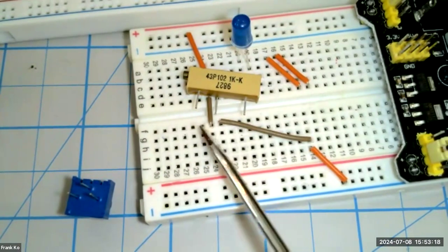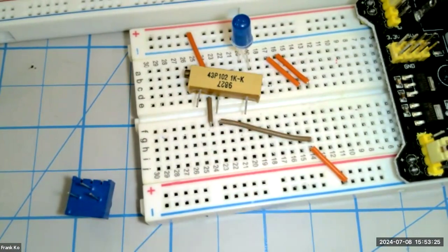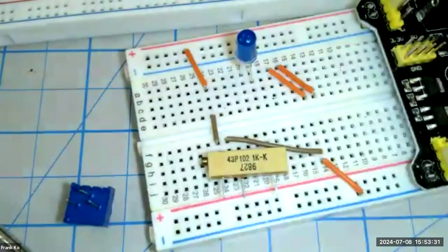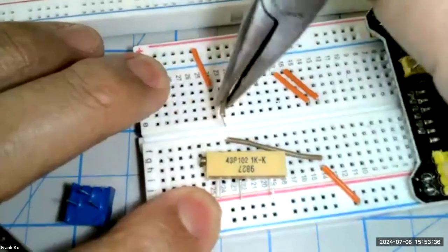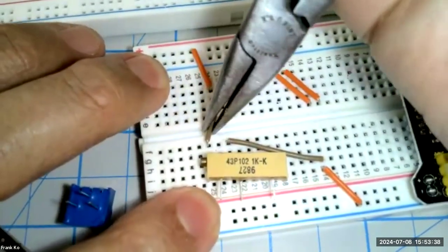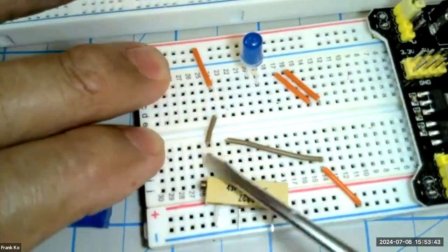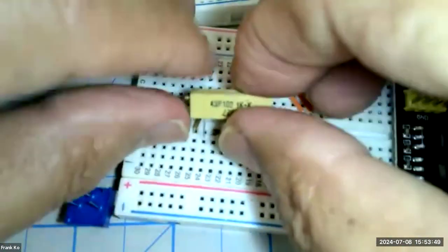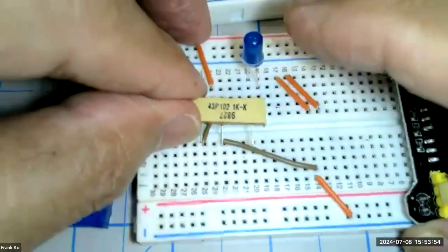So I have to create a larger gap on my breadboard in order for these jumper wires to make contact with these 2 pins of the potentiometer. That's easy to do. So let me go ahead and redo this for just a moment. Very easy. Just go ahead, grab this guy up, grab this guy, move this over one. Now I created a 2-row separation, and the 2-row separation allows, and let's see if I bring this down, does that match? Look very carefully.